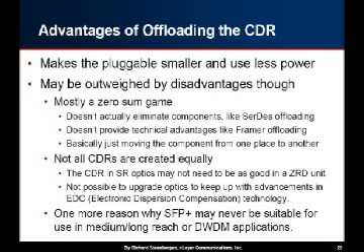And also, a lot of the CDRs, you want a different CDR for different functions. If you're using 10 gig SR or short reach optics, you may never have to do clock recovery. It may just never be a problem for you. If you're now running this over 80 kilometer DWDM, it might be a much bigger concern. So you might want a higher quality type of thing.